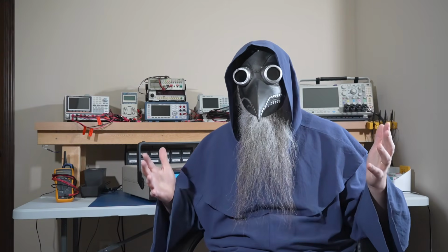We can learn a lot about analog encoding, timing, synchronization, bandwidth-limited modulation, filtering, impedance matching, and noise tolerance, to name a few things. If you can design a stable composite video generator, then you've touched almost every fundamental concept in analog and mixed signal electronics. Generating a composite video signal forces you to think in microsecond level timing, line and field structure, sync pulse shaping, color burst phase relationships, clock generation, and jitter. It's one of the few analog systems you can fully understand end to end. You can literally draw the waveform on paper and then build the circuit that produces it.